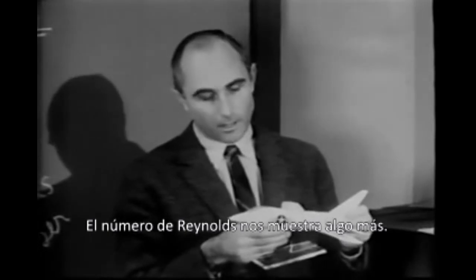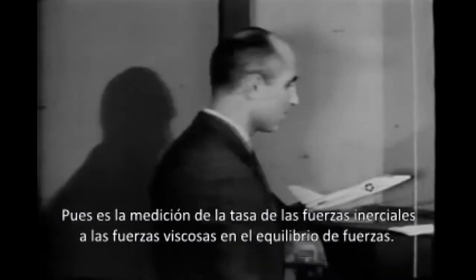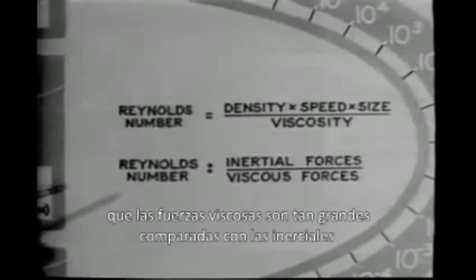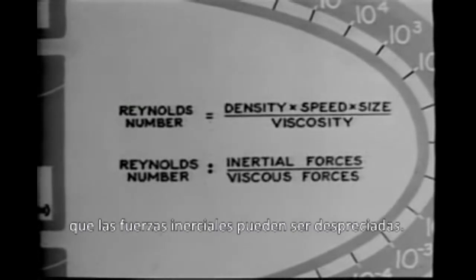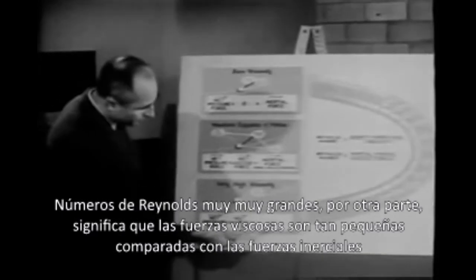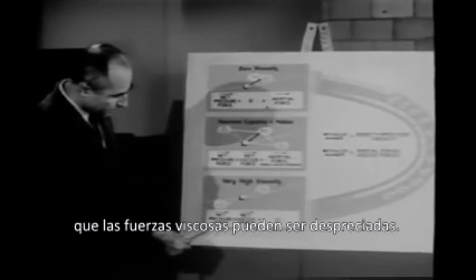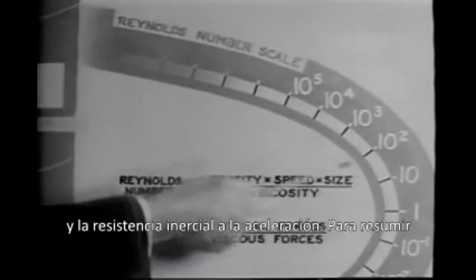The Reynolds number shows us something else, for it is a measure of the ratio of the inertial forces to the viscous forces in the force balance. Very, very low Reynolds number, for example, means that the viscous forces are so large compared with the inertial forces that the inertial forces may be neglected. We then have a balance between the net pressure force pushing on the fluid and the net viscous force resisting the deformation. Very, very high Reynolds number, on the other hand, means that the viscous forces are so small compared with the inertial forces that the viscous forces may be neglected. We then have a balance between the pressure force pushing the fluid and the inertial resistance to acceleration.